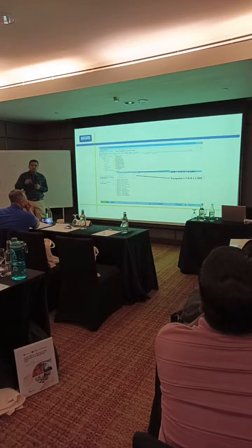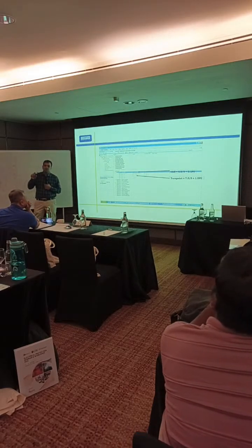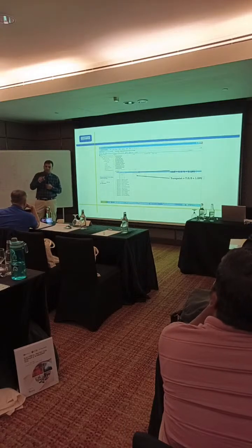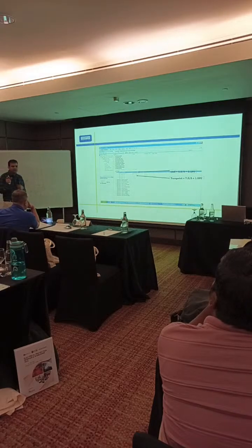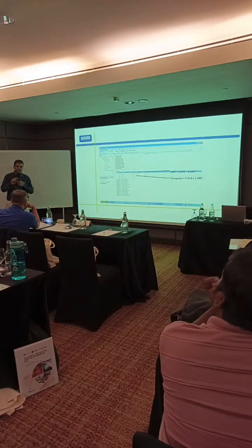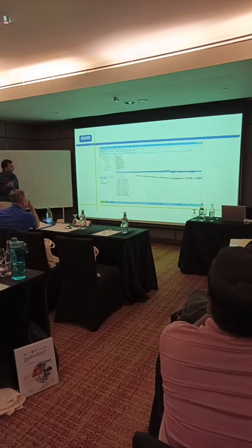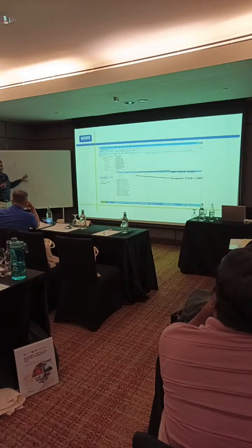So even the differential measurement will be in per unit for the transformer differential, the restraint current and differential current are measured in per unit, while in generator protection you will be finding it in ampere. So whatever the unit is, the calculation will be the same. Either it is per unit or ampere, the calculation method will not change. So you have to follow the same.